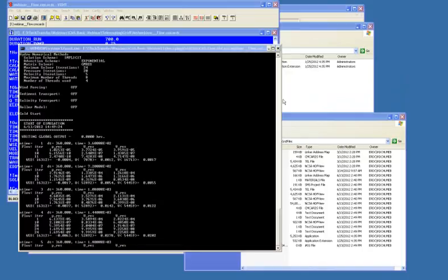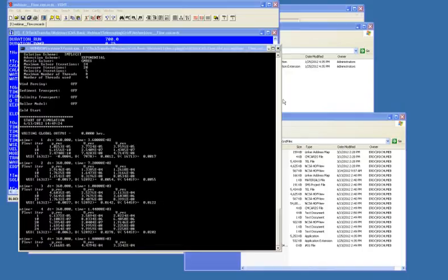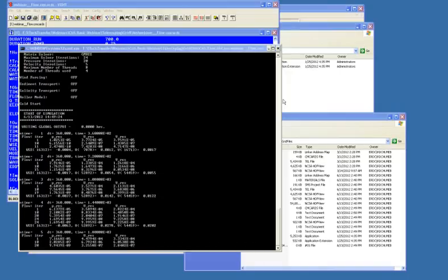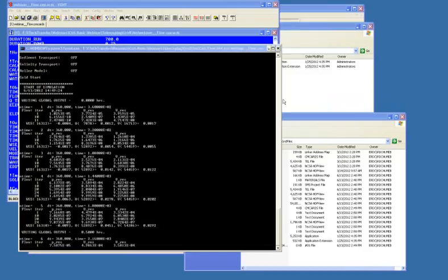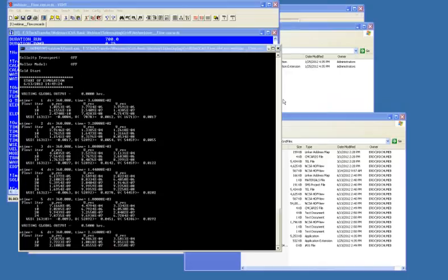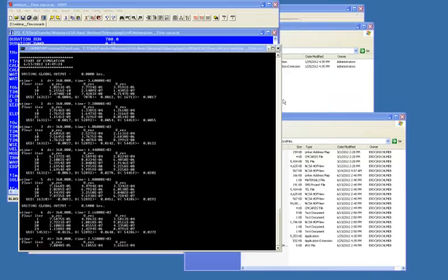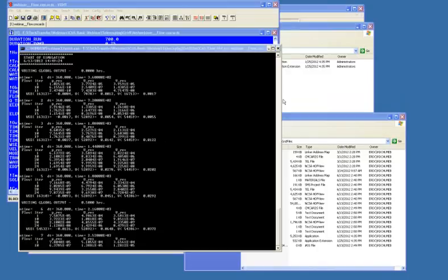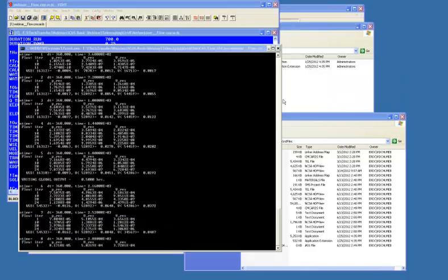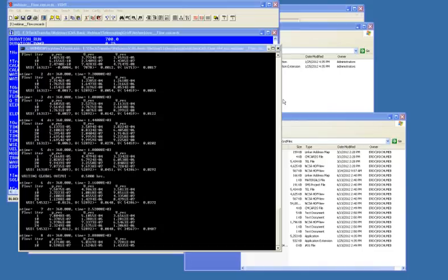Another question: you mentioned we cannot run telescoping grids in implicit mode, but we can outside of SMS. No, that's not what I said. What I said was you can run telescoping grids with the implicit model only, whether that's inside the SMS or outside the SMS. If we try to run a telescoping grid with the explicit model, then it does not know how to, it can't read the files, it doesn't know what to do. And so it'll error out very early. So you can run telescoping inside of SMS, outside of SMS, but only with the implicit model. Does that answer your question, Matt?